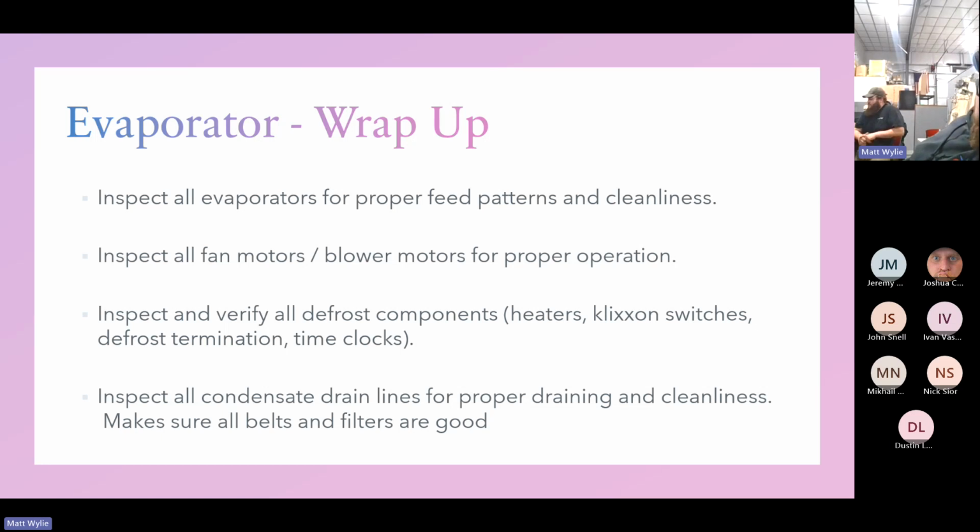On the termination too, if you ever have a freezer and you put it into defrost on the time clock and it goes right back into refrigeration, don't assume it's the time clock. If it has a termination, pull your X wire off your termination on your time clock and retry it. If the time clock stays in defrost, then you know for sure you have a bad termination.